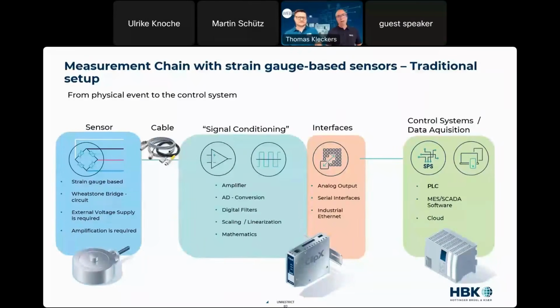What we always have, from the left side of your screen to the right, is a passive sensor for load, weighing models, load cells, or force sensors, also called load cells in English, but they are measuring units. And those sensors are passive. That means we need an external voltage to supply the sensor.